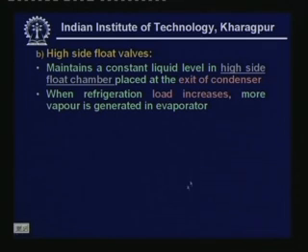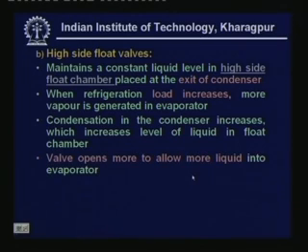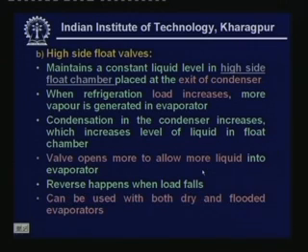Okay, I have already explained this. When refrigerant load increases, more vapor is generated in evaporator, condensation in the condenser increases, which increases the level of liquid in the float chamber. Valve opens more to allow more liquid into evaporator. But unlike low side float valve, the high side float valve can be used with both dry as well as flooded type of evaporators.